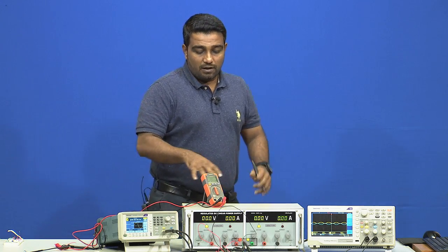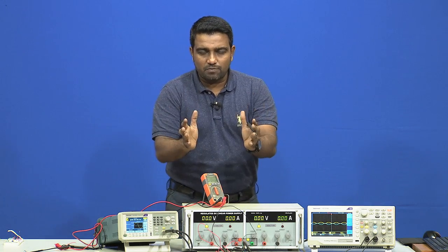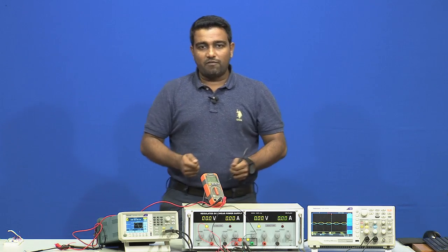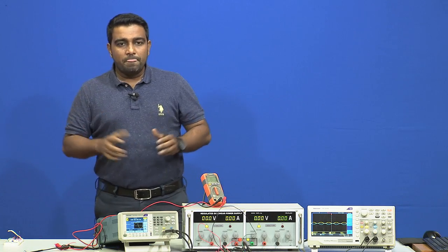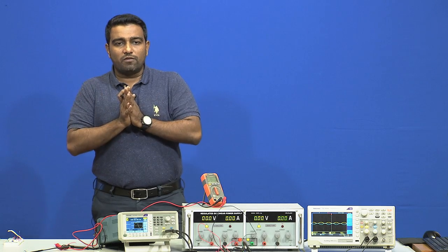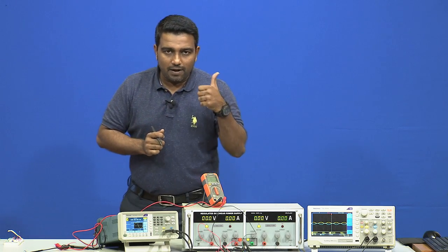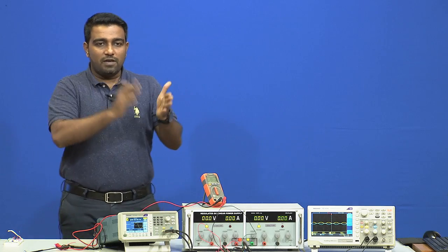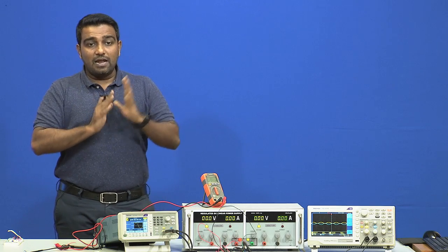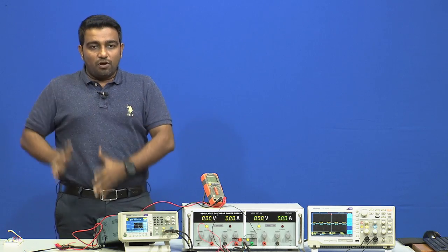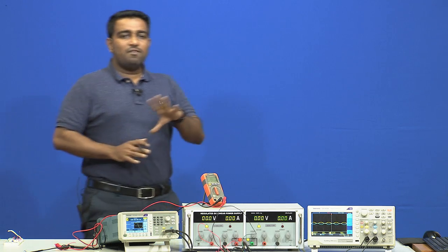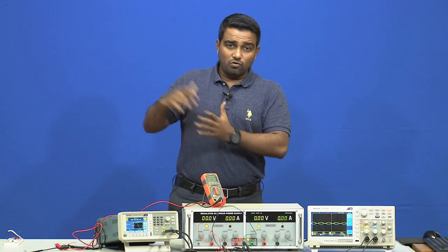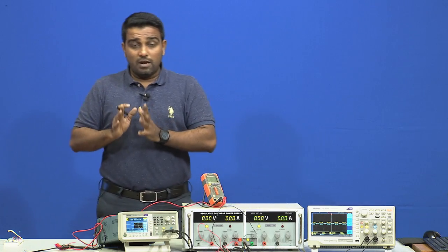So, like I said, we will break this experiment into a few parts, so that you can take a break in between after every class. So, for now let us quickly recall what we have seen. We have seen an inverting amplifier, we applied the input at an inverting amplifier, we measured the output, from that output V out by V in, we have measured the gain of the inverting amplifier, we have measured the theoretical gain of the inverting amplifier, and we already know that V out equals minus RF by R in into V in, that is the formula for your inverting amplifier.